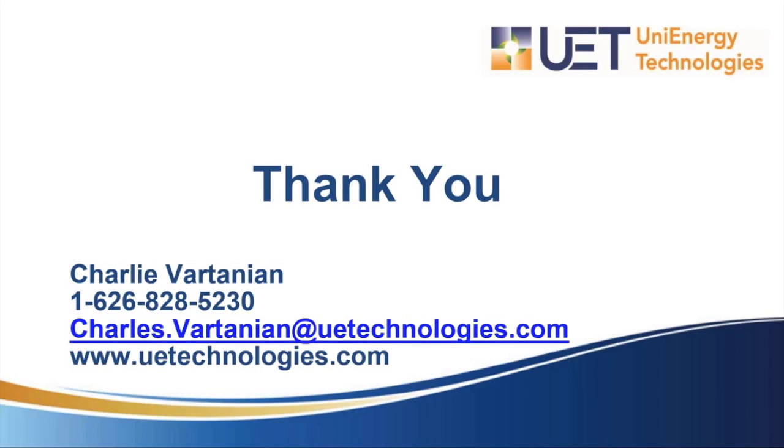First of all, what ramp rates and response times can be expected from flow batteries? This is Charlie speaking for UET, and this is shared by a number of flow batteries. At the DC level, we've got 1 to 10 millisecond response. At the system level, inclusive of controls, 100 milliseconds. And that's going from anywhere within the allowable state of charge, which is 0 to 100%.